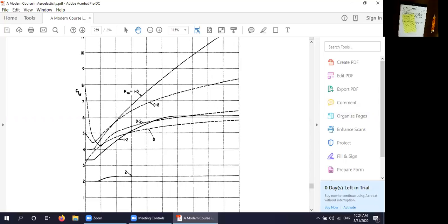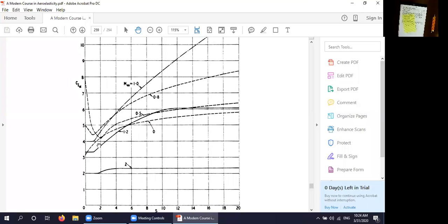But strictly speaking, what happens at time t equals 0, remember piston theory is supposed to give the right answer at short times. It's 4 over the Mach number, but 4 over 0 is a very big number. There's actually a delta function. There's an infinity. The incompressible flow theory itself actually breaks down at short times, which corresponds also to very high frequencies, and it has its own difficulties. That usually is not mentioned in the literature, particularly by those people who like to use incompressible flow theory. But strictly speaking, at short times, the incompressible flow theory has a problem.